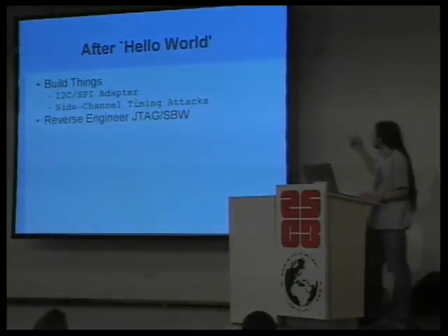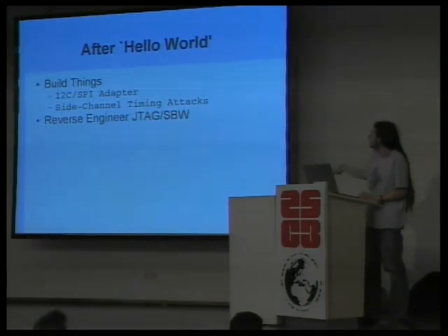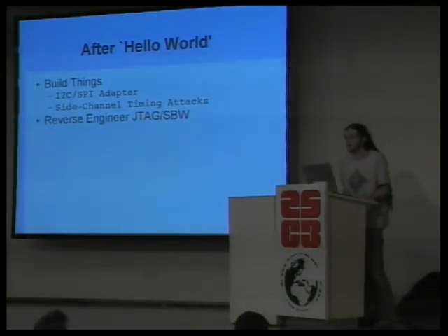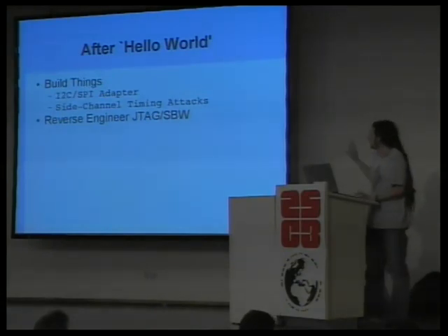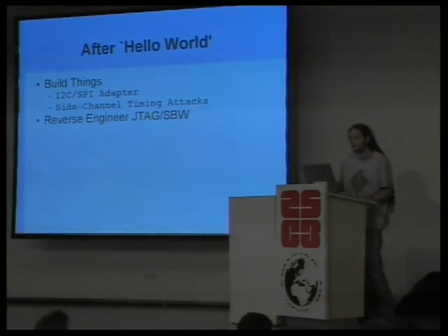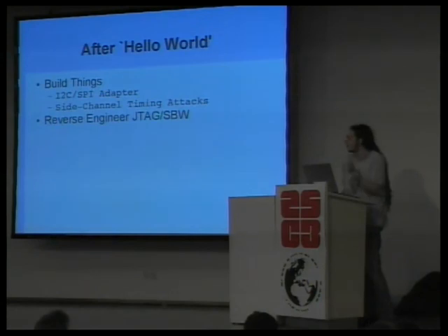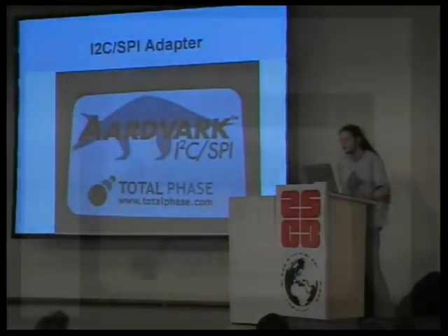The other thing you can do is reverse engineer the actual JTAG standard for the MSP430. Because while they've published enough to tell you how to program a chip, the documentation hasn't been updated in quite a while, and it doesn't specify how to program the new 20-bit chips, the MSP430X. So you could modify this device to, say, spit out debugging information, to do things like that. And you can add support for proper JTAG, whereas it only supports SPI-by-wire, the 2-wire JTAG standard.